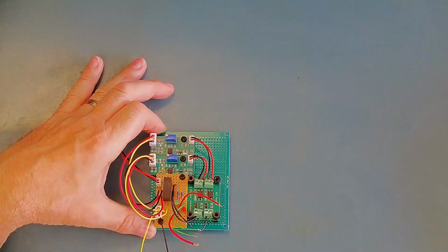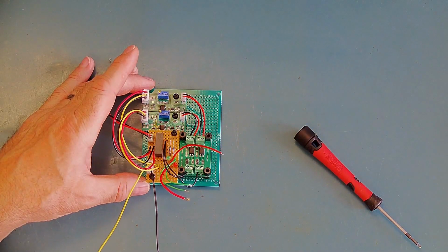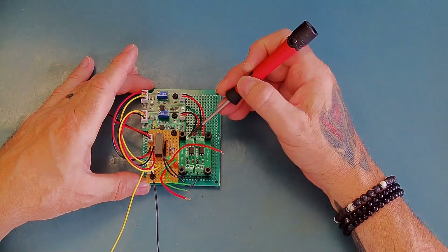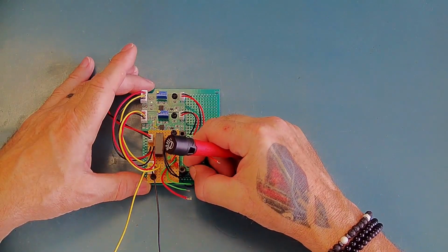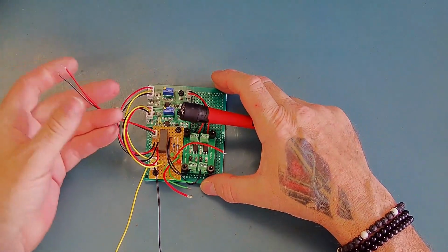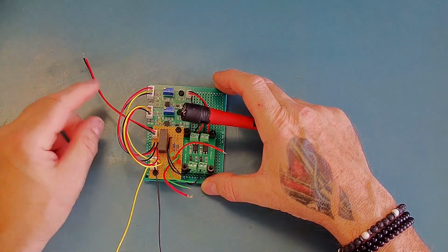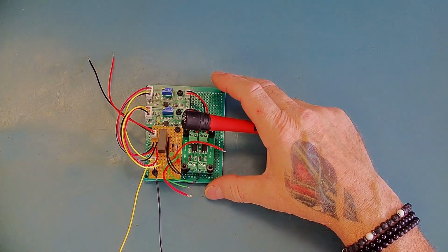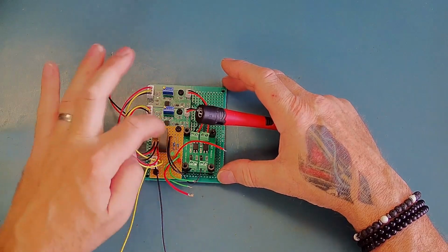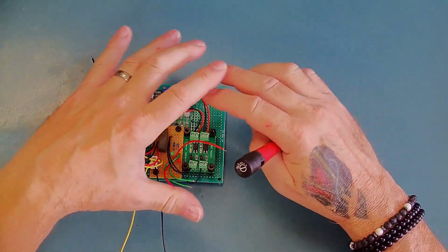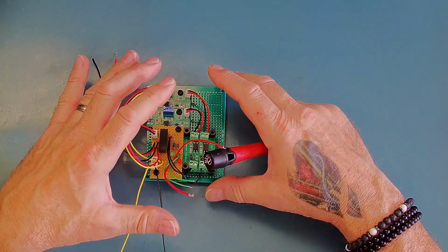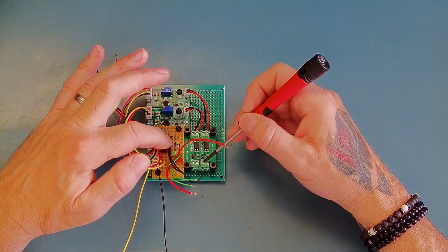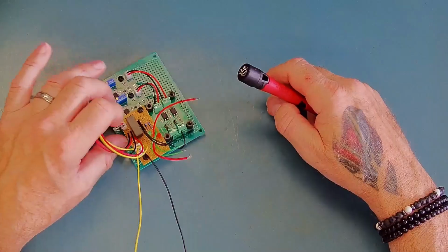Let's just zoom back out again. It's coming from this yellow wire here, which will be the sense wire to the actual meter itself. And then I've got the 2 opto-isolated modules here, and then the 2 outputs here. This is supplied from 5 volts, and it can be any 5 volts because it's going into this DC to DC converter. So the power for this module is all supplied from this converter here. So this is actually totally electrically isolated. The only thing that's actually referenced to the common ground reference will be the outputs of the opto-isolators.